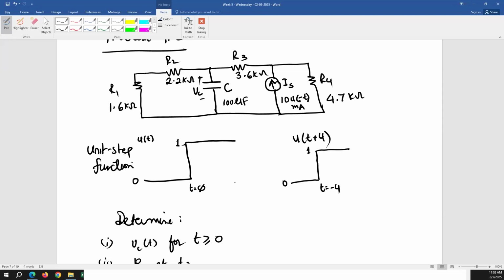So we are looking for that, and we can find that voltage drop if we find the current passing through R1 and R2. And of course, R3 carries the same current because all of them are connected in series if the capacitor is open circuit. To do that, we can easily use current division since we know the total current. So we can apply current division and find what current is passing through those three resistors. So let's do that.